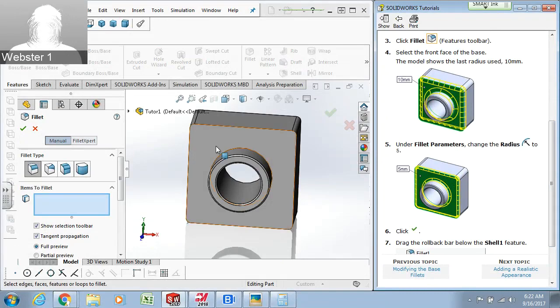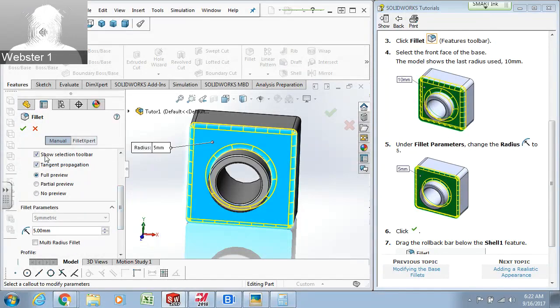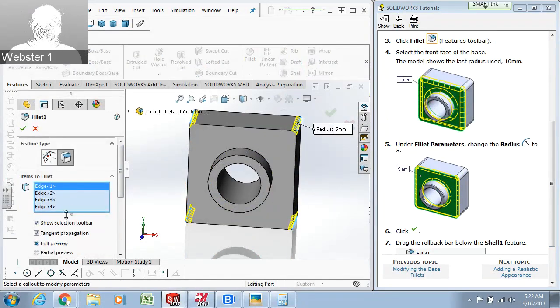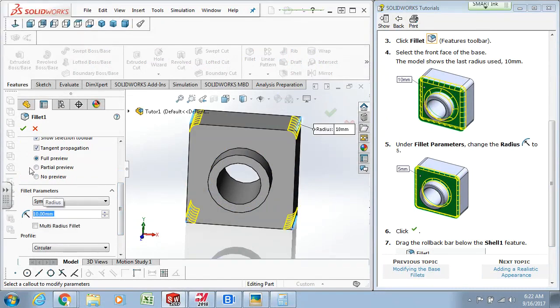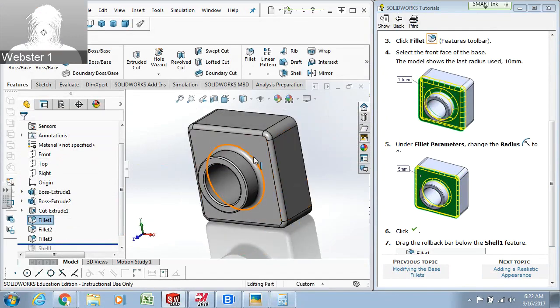So you're going to do a 5mm fillet to the face. So that's what that is. So we hit the green check mark because it's already at 5. So there's 5. And then they want you to go back into this one on the corners and edit that one to be 10. To change those to be 10. So now you've got 5 for the face fillets and 10 for your corner fillets, and still 1.5 for there. So now you have 3 fillets.